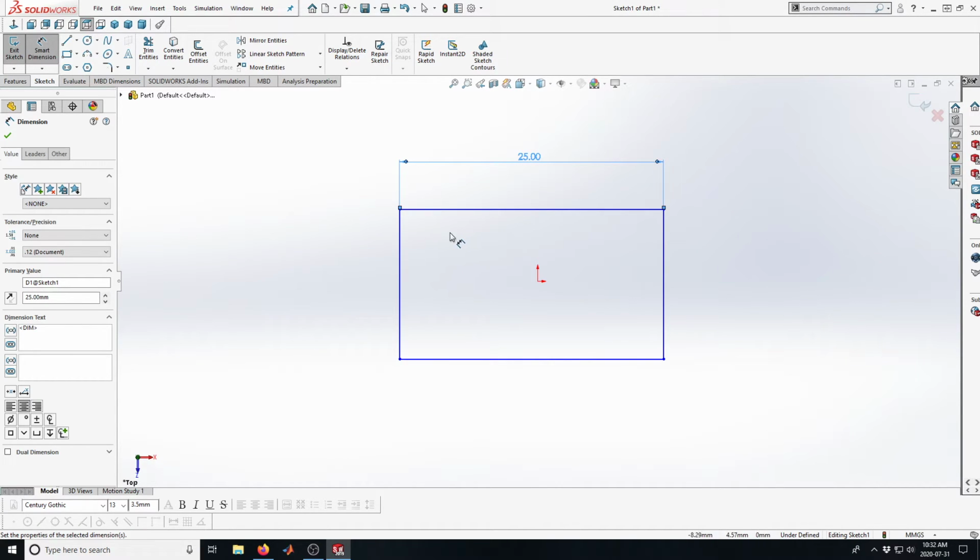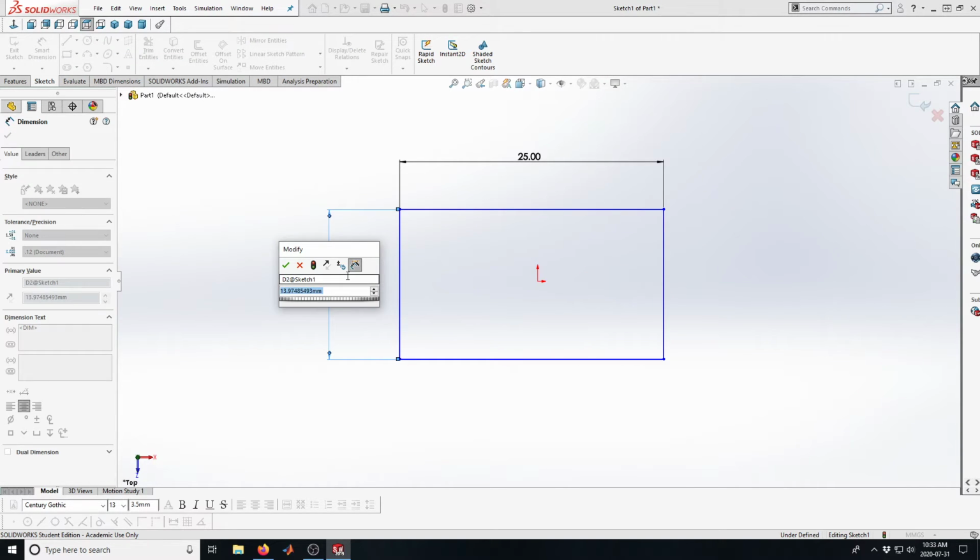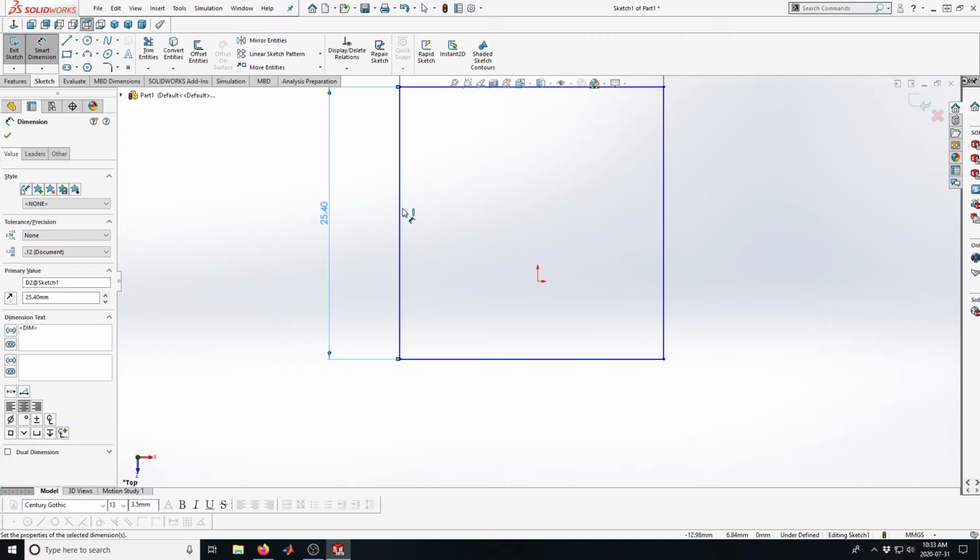The thing is, it doesn't look any different because when you start out a drawing, it's completely unscaled, in the sense that the dimensions you enter are real, but it doesn't care whether you make something that's a mile, a kilometer, or a micron. There's no limit to what dimensions you can put in here. So I put in 25 millimeters, since my setup defaults to millimeters. I could put in 1 inch just by typing 1 in. And it knows that that's 25.4 millimeters.